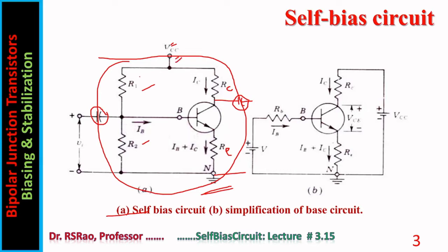Here is VCC, it drives some current like this. If capacitor is not there, then some of this current may enter into the source like this. Current entering into the source means spoiling the source. Similarly, DC entering into the load means not only power loss, reduced efficiency, but also it leads to unwanted, unnecessary complications and repercussions.